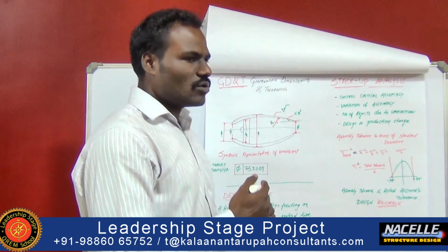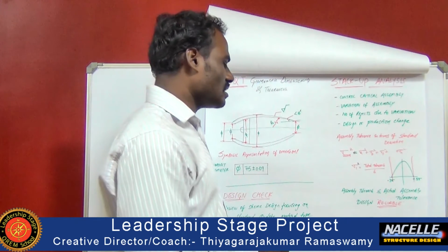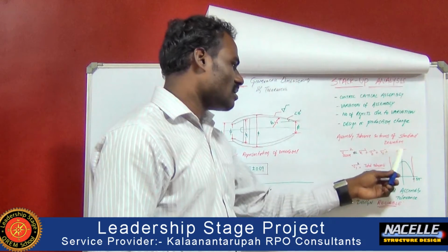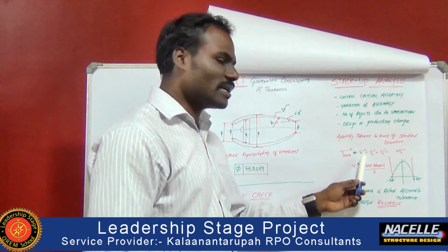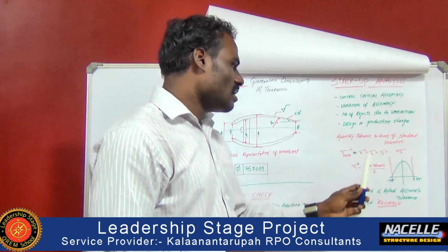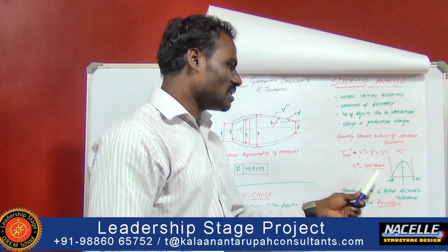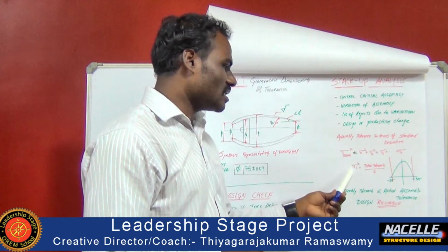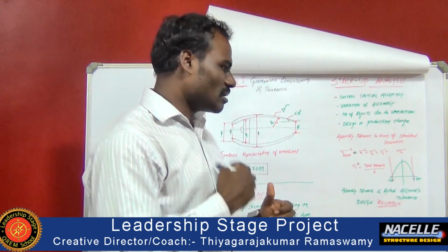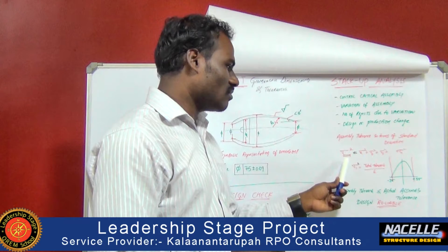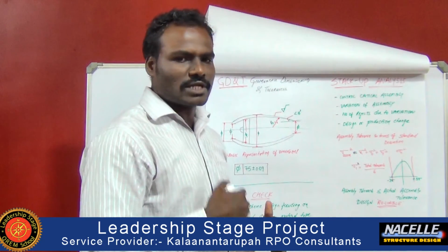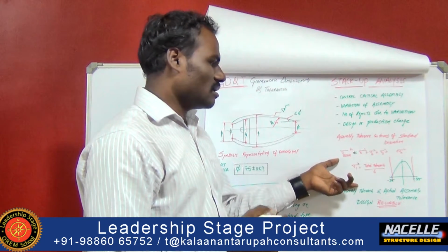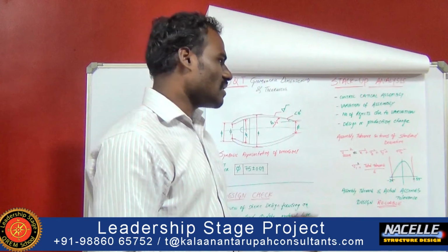Usually, to calculate the stack-up analysis, first find out the standard deviation of each and every part of the component, then sum them up and square them, and divide with respect to the 6 sigma ratio. After getting the value of the standard deviation, it has to be multiplied with the value we have obtained, and divided by 2. That leads to the stack-up, the tolerance value.